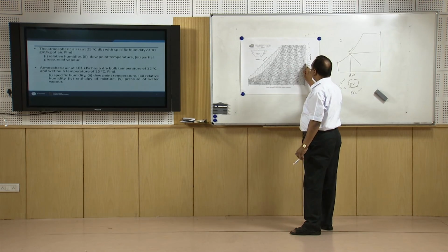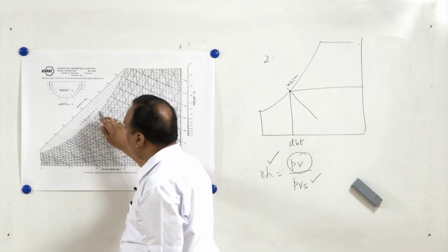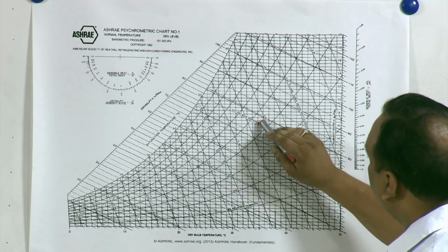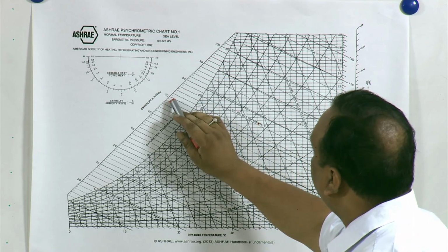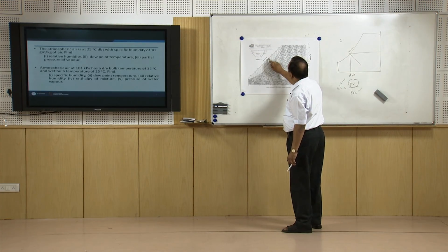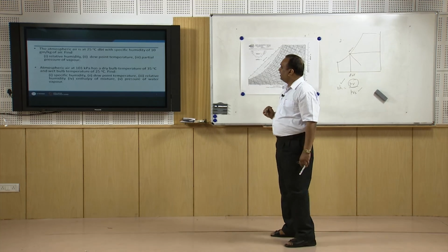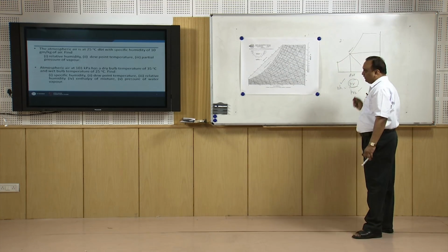For example, specific humidity on going into the right hand side, then the dew point will go to the left hand side, around 22 degrees centigrade. Relative humidity we can take from here, it is around 45%. Enthalpy of the mixture, we can take as 72, 74, 76, about 76.5. And for the pressure of water vapor, again we can use the same formula, PV by PVS.